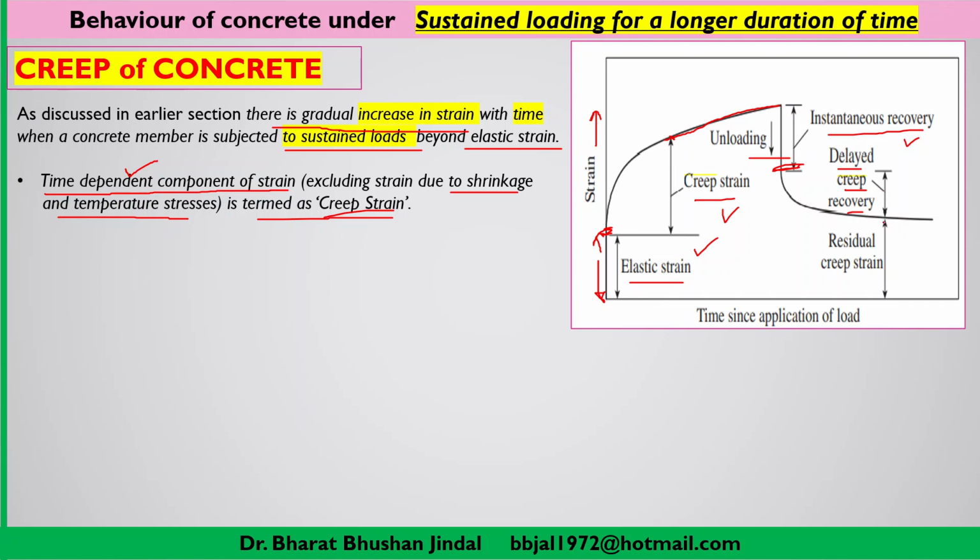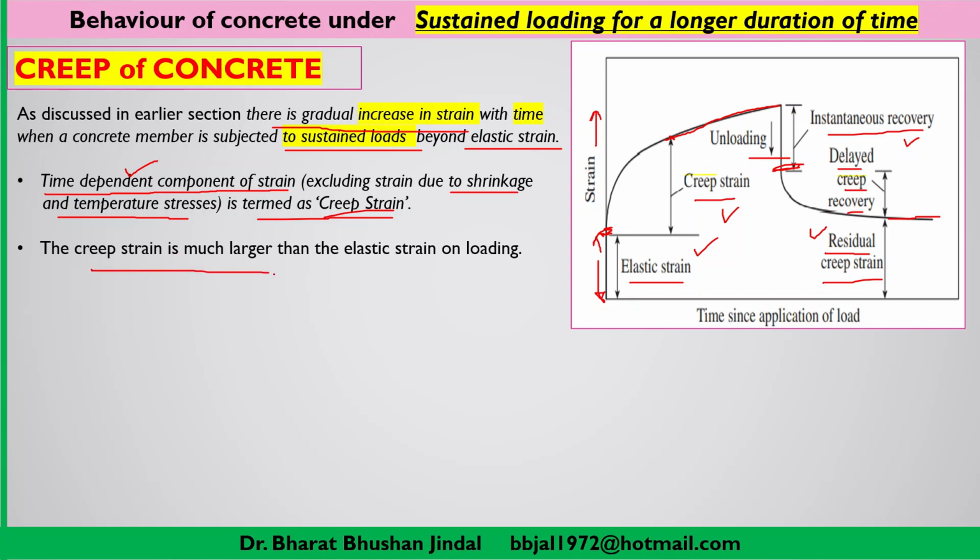And after that you are observing here that the strain is almost constant, so it means some creep strain just remained within the member, which is termed as residual creep strain. So from this graph we can easily understand how concrete behaves under sustained loading of longer duration. Now this creep strain is much larger than the elastic strain on loading. So this is the important point.